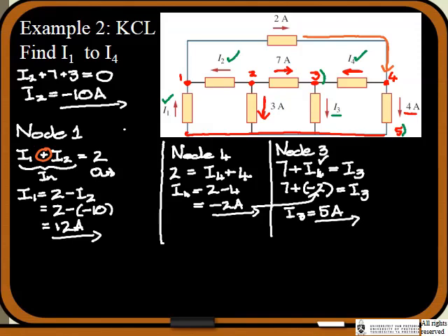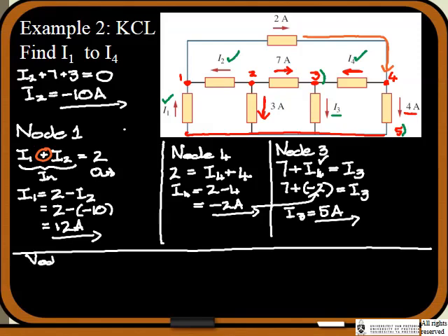What would happen, let's just draw a line here. What would happen if we were to solve for I3 using node 5? Because it must work out obviously on the same answer. So if we write down for node 5, all the currents coming in must equal the currents going out. What's coming in? Let's start on the right hand side.